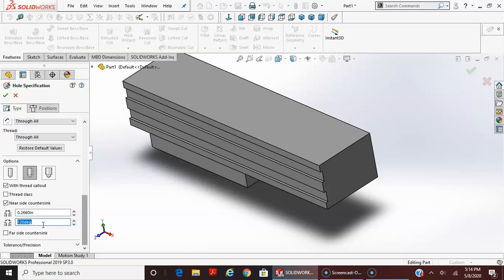The problem with a smaller angled spot drill like a 90 is that it doesn't engage the drill at the tip of the drill. It engages the drill in the middle of the cutting lips, and you have to get down, not that deep, but you're going to be doing some cutting with the drill on specific locations on the cutting lips, instead of over the entire face of the cutting lip.